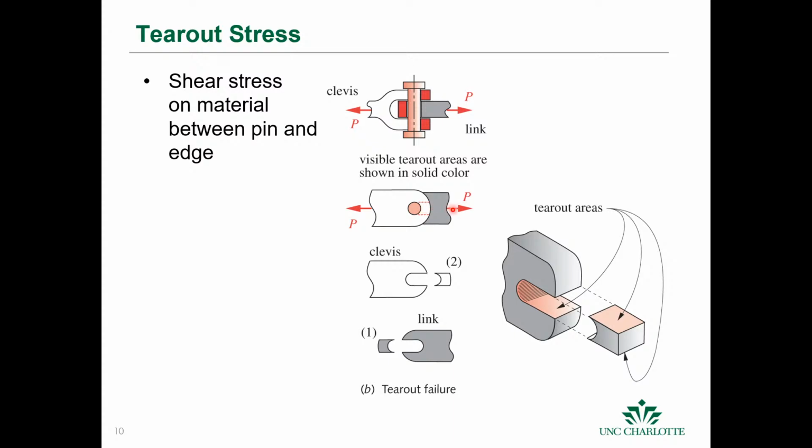This is a question that was on the PE exam actually. So it's a pretty classical failure mode, and it acts in shear on the faces that are orthogonal. So what people will say for a rule of thumb is make sure you have at least the diameter of the pin worth of material over here, so that you can prevent tear out.